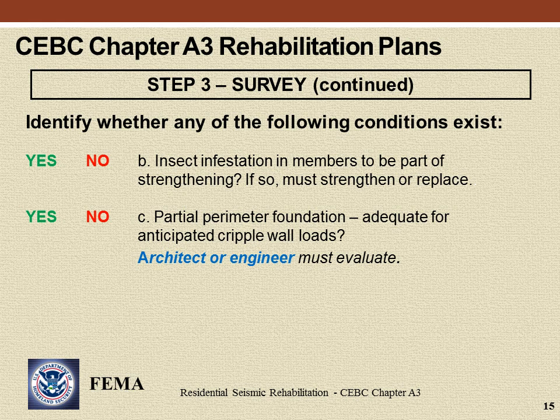Step 3, Condition Survey continued. Item B, similar to Item A, affects the framing to which rehabilitation work will be installed. Note also that termite repairs to the cripple wall or foundation can sometimes result in a modified configuration that requires evaluation by an architect or engineer.